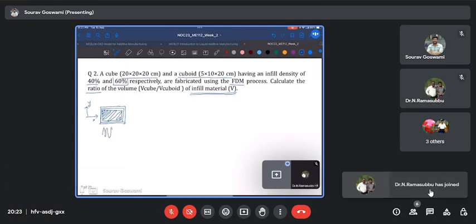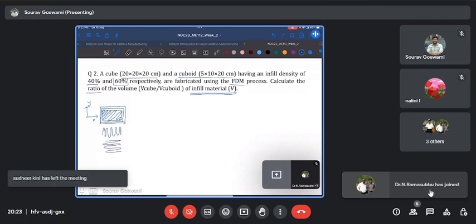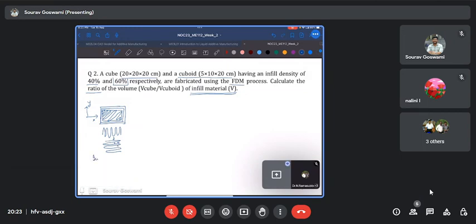This may even progress along any axis. But you see that these are discrete paths, and usually based on the infill density, they will not overlap unless the density is 100%. So there is some area where I am depositing material. Say this is FDM, so filament based material. But in all of this remaining area, which I have highlighted in red, it is actually a void.